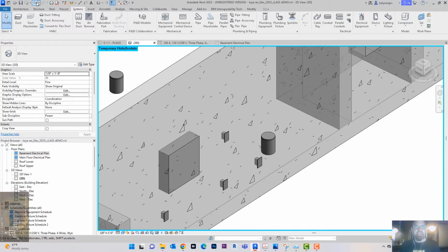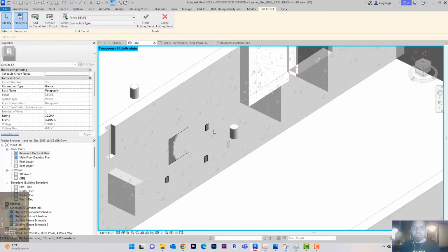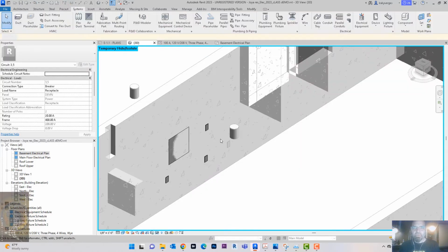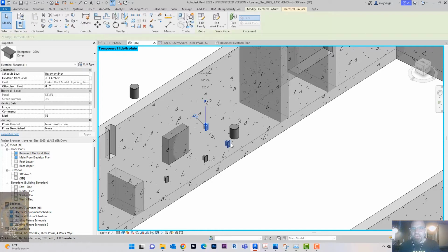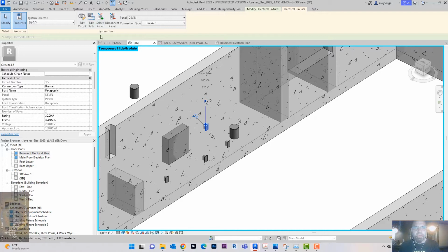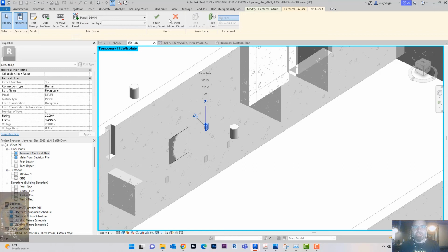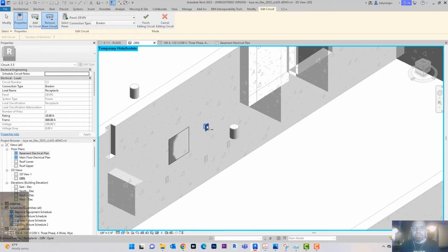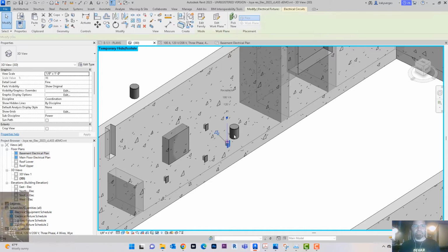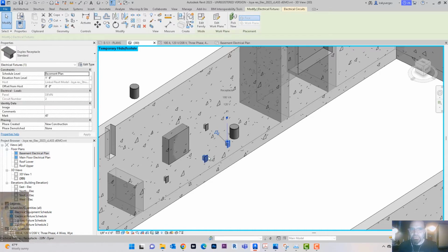I already did that since I copied this file. I basically already had this pole set up to 2 poles. So keep that in mind. If your dryer or your stove does not connect to the circuit, you have to change the pole to 2. Okay, let's go back and check our...